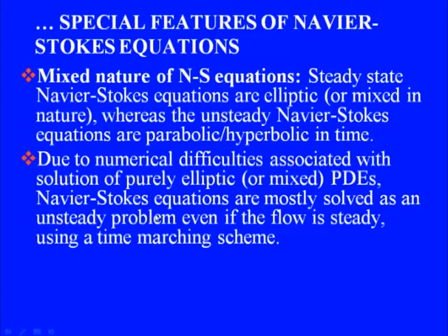In fact, Navier-Stokes equations are mostly solved as an unsteady problem, even if the flow is steady, using a time marching scheme. And we have to integrate in time for fairly long time instants. So, the long time solution of this transient Navier-Stokes problem would yield us the solution of the actual steady state.